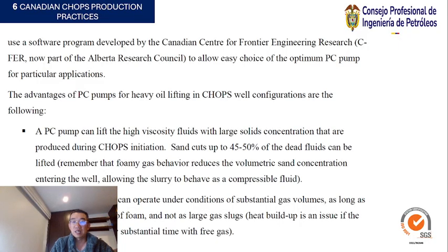Sand cuts up to 45 to 50% of the fluid can be lifted. The PC configuration can operate under conditions of substantial gas volume as long as the gas is in the form of foam and not as large gas slugs.